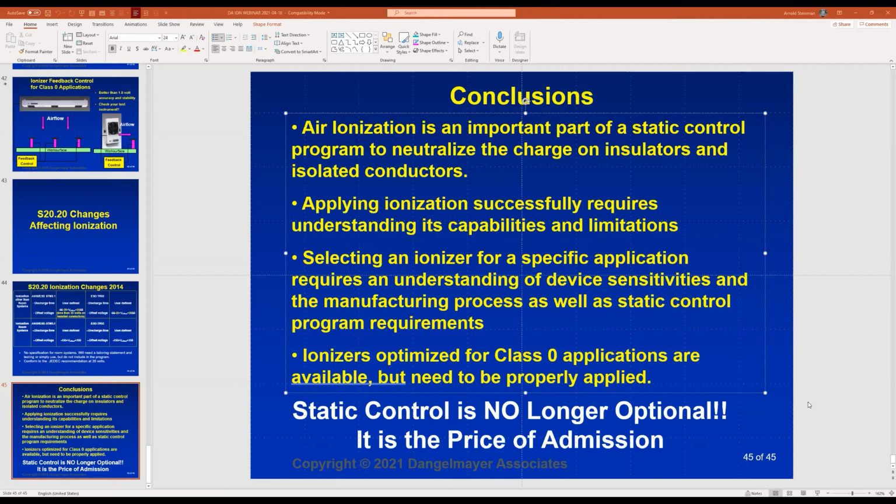The interesting thing is years ago, we did a little Pareto chart of maintenance issues. And no surprise to us, the largest bar on the Pareto chart was no maintenance at all. So that's still a problem. Doing maintenance is really simple. It usually involves a swab dipped in IPA, and you just swab the points with it. It's not very difficult. But basically, we see a lot of ionizers that aren't getting the maintenance they need.